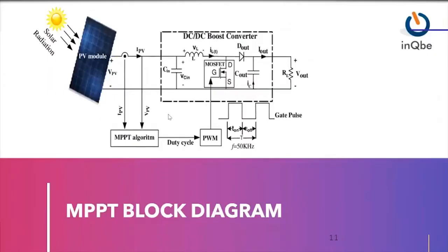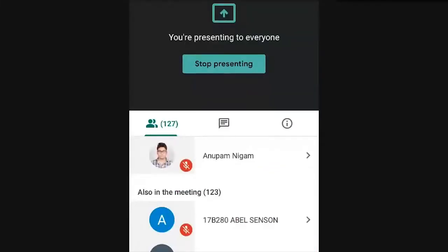Okay. This is a circuit for applying MPPT. It is a simple circuit; yesterday we did a boost converter. In a similar way, here instead of a DC source, we have a solar PV. We can vary the duty cycle to control the power flow from the PV side to the load. That means the duty cycle can be adjusted to vary the power flow. That means we are not adjusting the load.